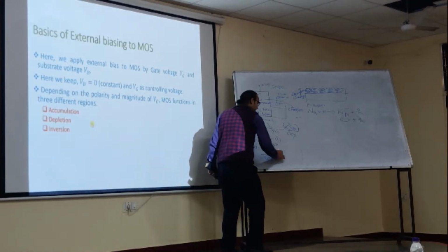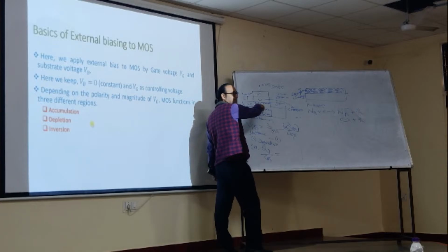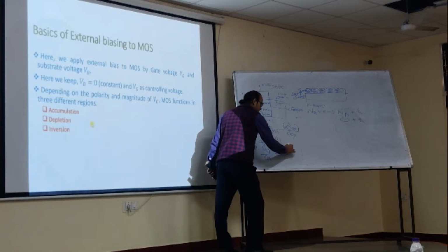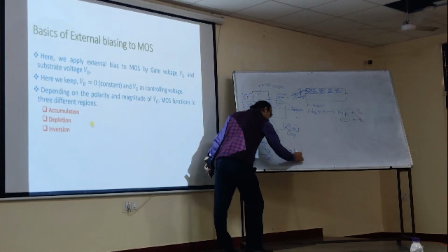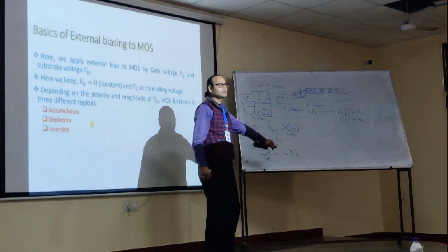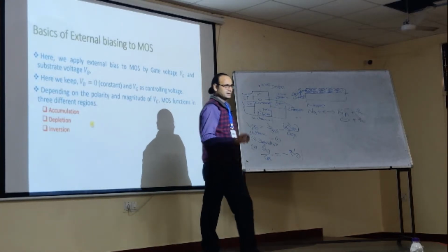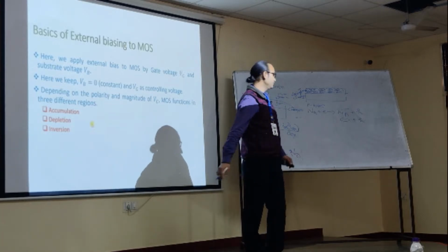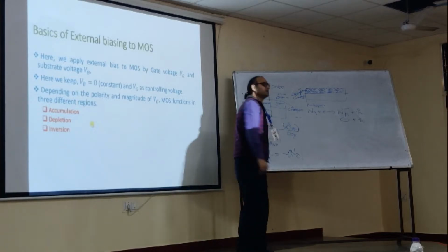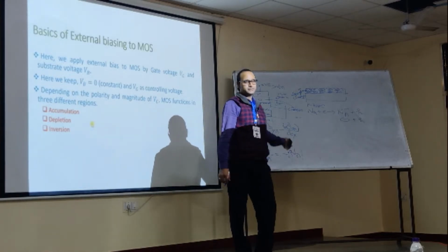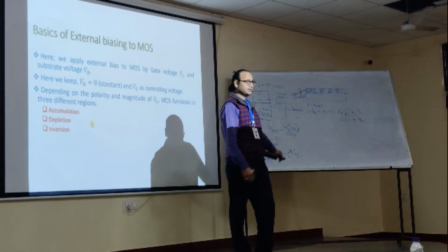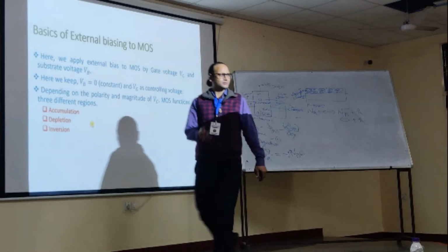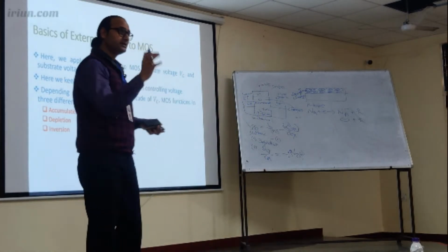So what will be Qd? Obviously Qd is a negative charge, and it involves Nd, which is just the doping concentration, number per unit volume. So I should multiply it with q. Now it becomes charge per unit volume. If I want to make it per unit area, nothing else, just multiply it with W. Like that, we analyze the things and we derive.